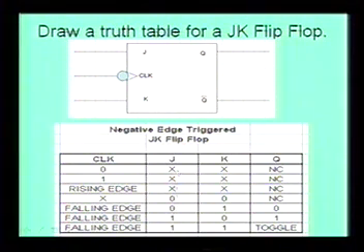That would be if J is a 0 and K is a 1, then Q would be a 0. And if J is a 1 and K is a 0, then Q would go to 1. And then you have a falling edge. It'll toggle: if J and K are both 1s, then every time it goes through a falling edge, Q will just toggle on and off, and that's how that works. You might ask, why would you even need a JK flip-flop? Really, it's because you want to save a bit. It's a type of memory address. I think we covered this previously.